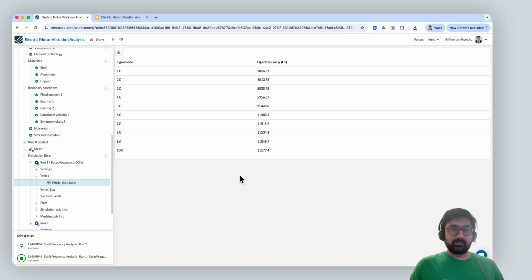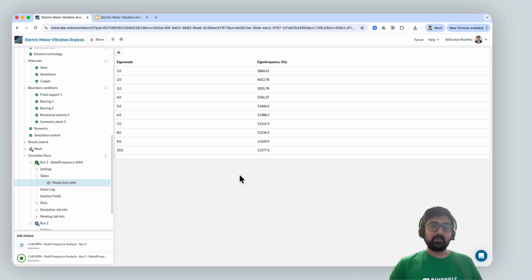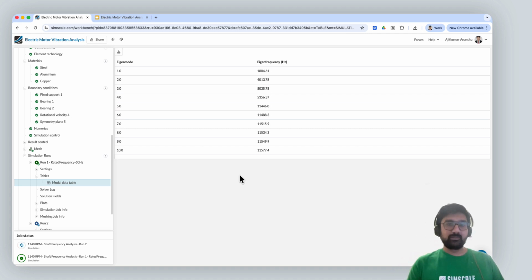To extend this to the variable frequency drive objective, we would need to run this case similarly using different RPMs. The idea here is to ramp up the frequency and the RPM to see up until which point the motor can operate safely. This is relevant in cases where the motor is subjected to a variable frequency drive and the frequency changes during the operation.